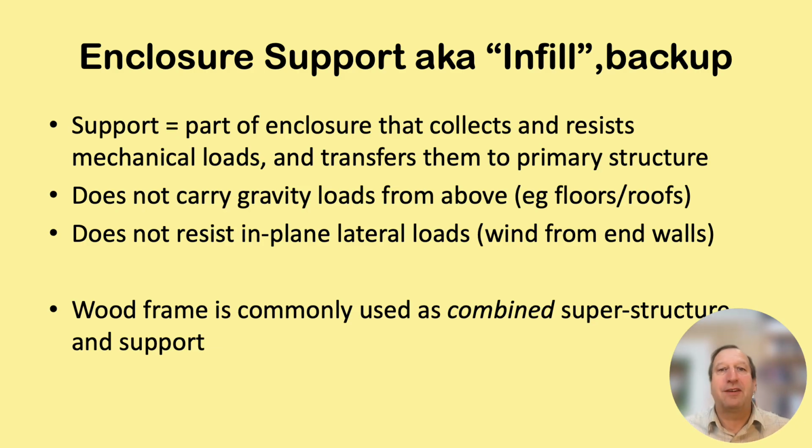It also doesn't take lateral out of plane. So think of the enclosure as a flat, say a wall or a flat roof. It's not taking the loads that are lateral and transferring them to the superstructure. The superstructure, its bracing, its moments, its shear walls are taking those and carrying them down.